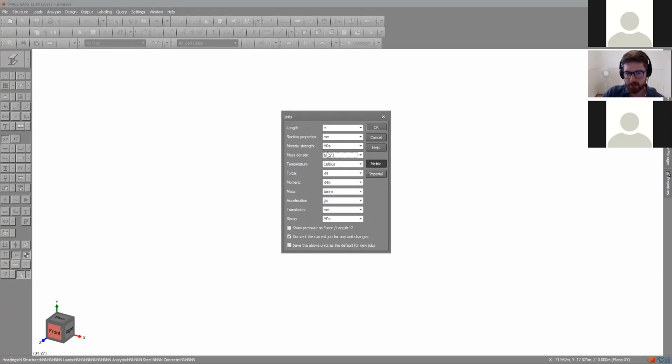Again, that's a pretty natural way to define those units. The thing that might trip you up, or what gets students in my course in third year when they start comparing their computational results to their hand calculations, is the kilonewtons and kilonewton meters. Kilonewtons is not used in any of your analytical solutions. It doesn't sit in the SI unit or the Newton millimeters consistent units, but it's a very natural standard kind of dimension for a structural engineer.